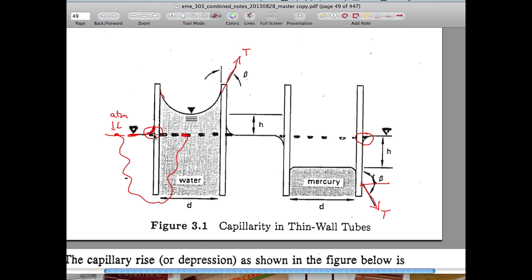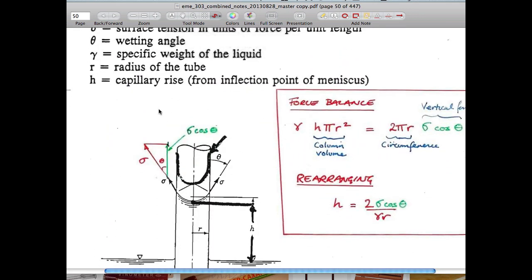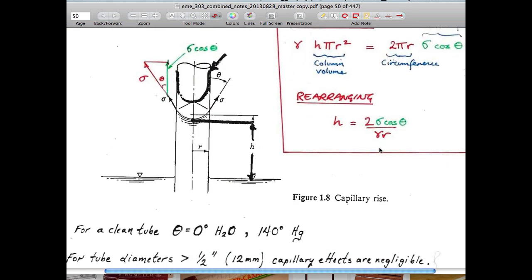So that physically means that you could cut off this tube at this point here and lift this whole column of fluid upwards and do basically a force balance on that. So that's the standard analysis that's applied to this. So that's the idea here. So you can cut this tube off at this particular location. You can remove the fluid from below, and around some average height of this thing, you can basically look at